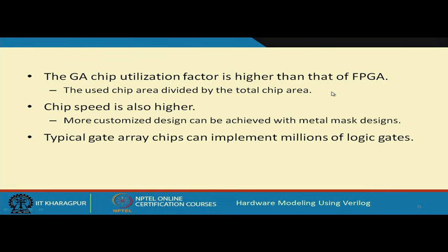Because in the FPGA chip, the field programmable gate array, if you recall, there was something called the configuration logic block, the CLBs. Inside CLBs there were the lookup tables or LUTs. Apart from the LUTs, there were a large number of other circuitries as well, a lot of multiplexers, some flip flops, whether you need them or not, those circuits are also there.